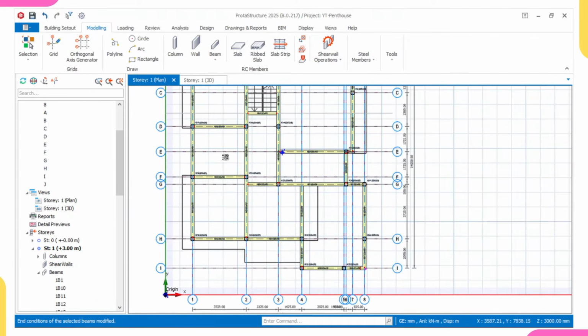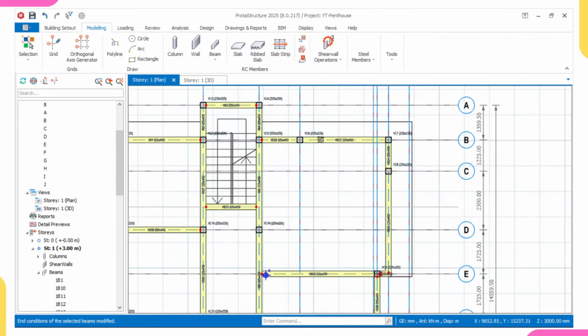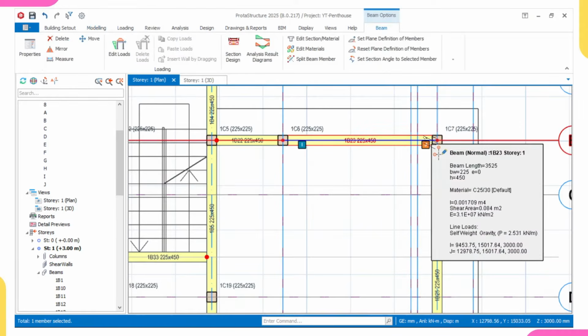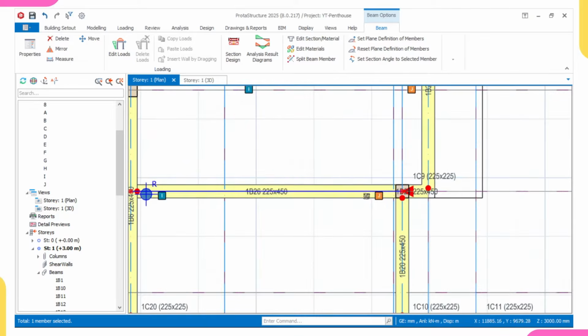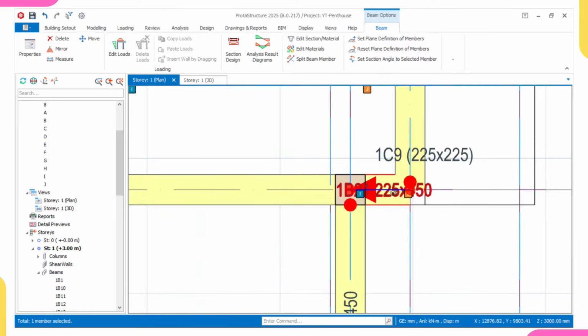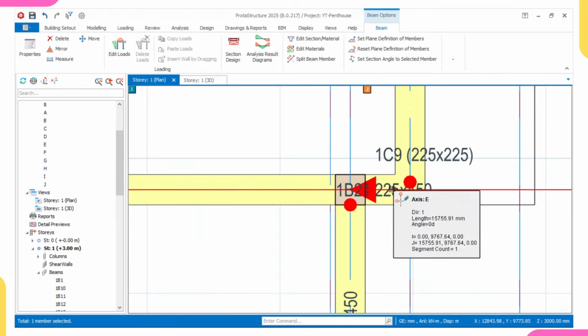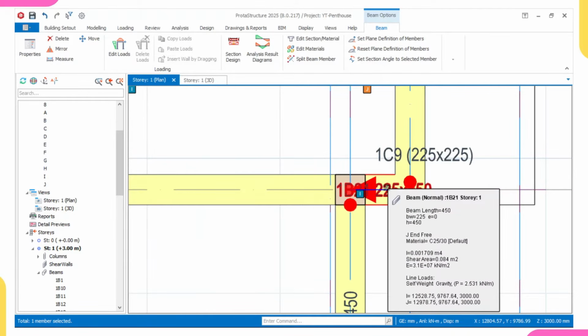Then the next one is to hinge my J members. So here, this is my J member. I will not hinge here because there's a cantilever here. Please don't hinge your cantilever, because a cantilever will definitely have a top moment.